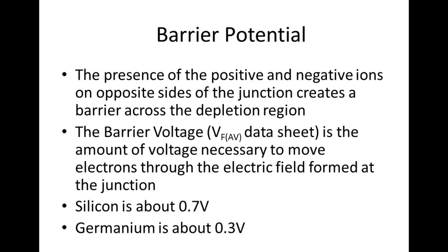In fact, we had flashlights at US Steel that ran off D-size batteries. And we had tons of radio controlled cranes that ran off little NiCad batteries, and the NiCad batteries only put out 1.2 volts per cell. So what would happen if you went over to 2 NiCad batteries? They were a lot smaller, but your flashlight was real dim. If you used 3 of them, you got 3.6 volts instead of 3 volts, and it got real bright. And if you bumped it against something, it would blow.